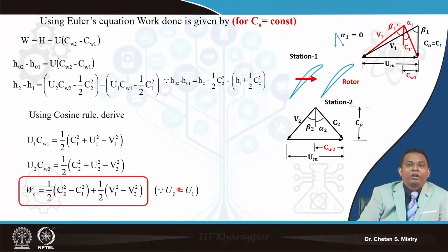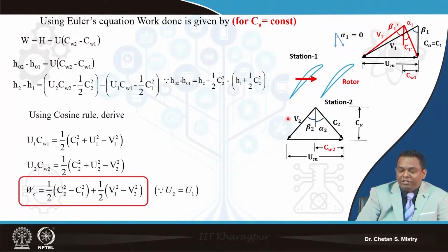But at this moment, in order to understand, this represents the third way of work done. First we can represent it using aerodynamic fundamentals. Second, using aerodynamic work done, and this is represented in terms of kinetic energy, which you already know. Here, this represents the relative velocity at the entry and this represents the relative velocity at the exit. We realize the relative velocity at the entry is larger and the relative velocity at the exit is smaller. That is what is responsible for doing the diffusion work.